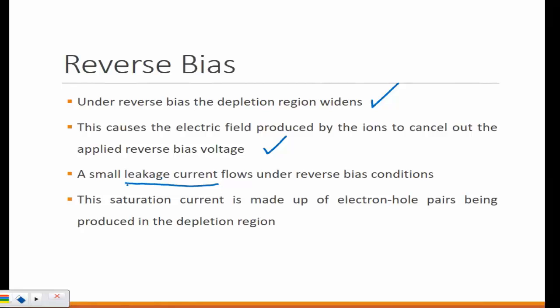So you will quite often hear this term leakage current. It always means that it's the unwanted current that will flow through the component under reverse bias. And you can test it too, but most of the multimeters cannot go a lot lower to like nanoamps and microamps. You may see 0 on their display.